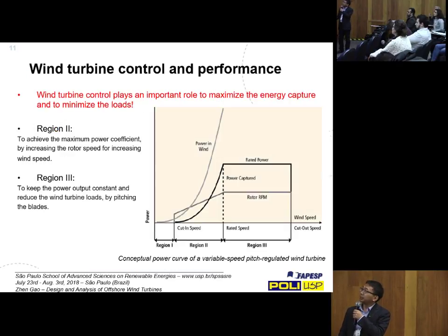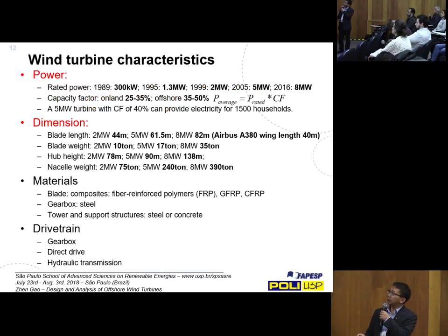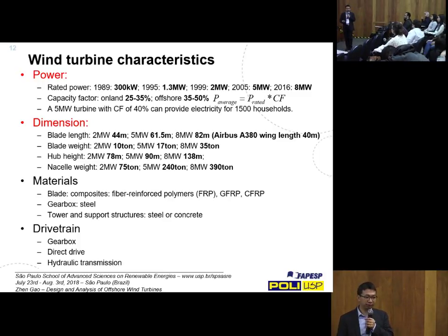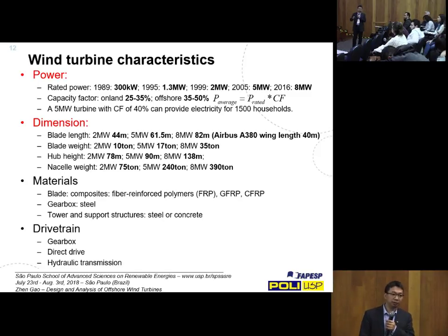Myself, I'm not an expert on wind blades. What I understand is that the turbine size is mainly limited by manufacturing issues. If you have a large turbine size, you have a very long blade. And for offshore, of course, there are issues about transport and installation, particularly for onshore application. But for offshore, I think there will be no problem. If you have a manufacturer close to shore, then you can bring the turbine blades to the site by boat, and then do installation on site.